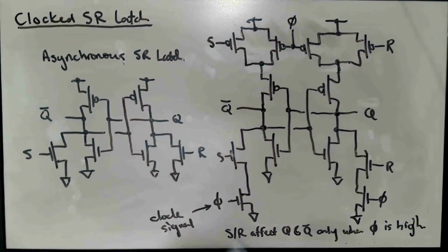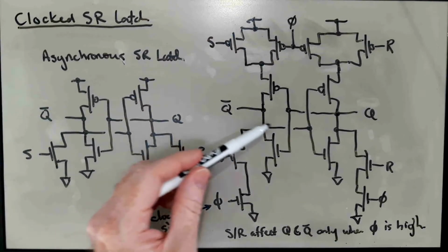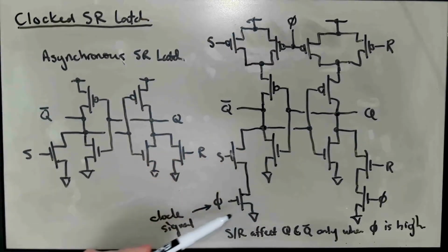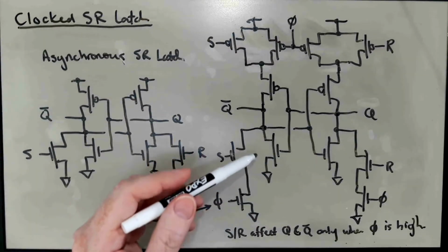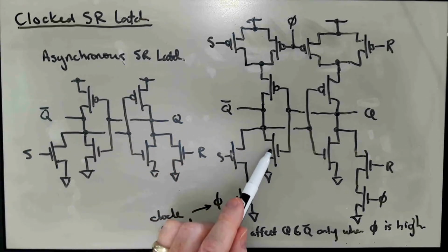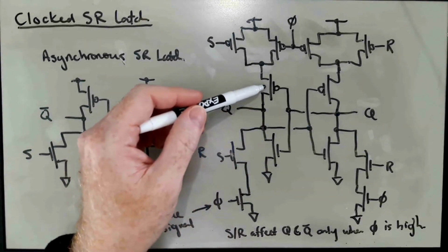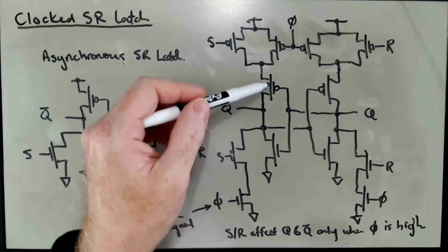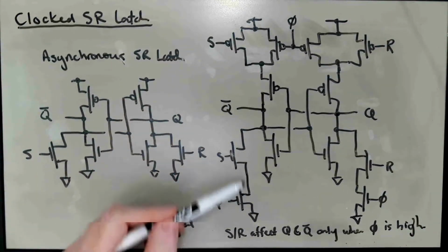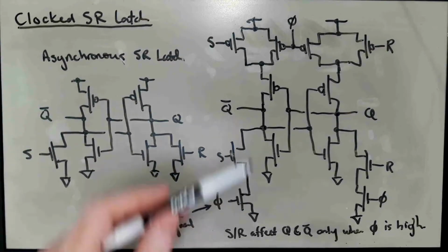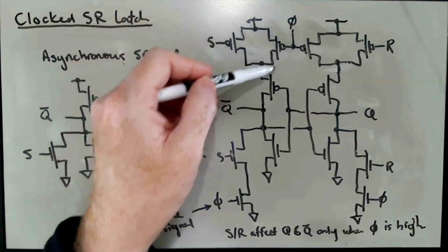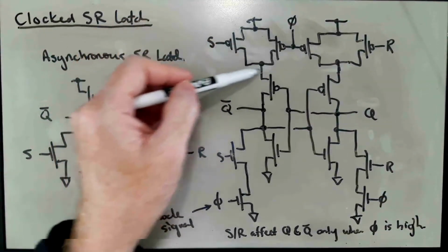So if you go through that exercise where we observe here's the pull-down network for each of the two gates that are participating in this, we have here two branches in parallel. One is the feedback that came from the feedback inverter, which is this transistor corresponding to this transistor in the pull-up network. And this in the pull-down network is in parallel with a branch that has two transistors in series. The corresponding piece of the pull-up network would be two transistors in series with this third one, and these are connected in parallel with each other.